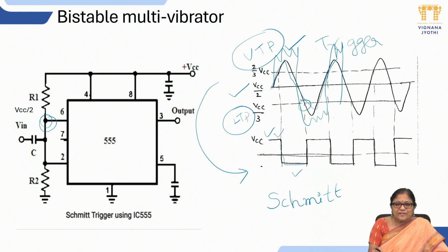So we have discussed three multivibrators based on the 555 and a few basic components, like two resistors, or sometimes two resistors with one capacitor, and the capacitor which is connected at the input is meant for cleaning any DC signal which is available in the input signal. To block or filter the DC, this capacitor is used.